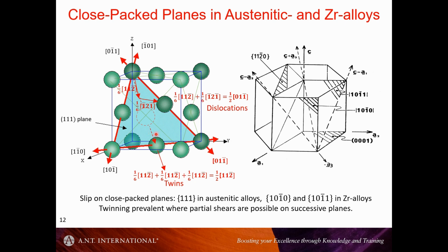In the case of the austenitics, I mentioned the twin operation, as you may or may not know, and again I can demonstrate this with some ball models later, or certainly during the presentation, but I'm also going to be attaching some YouTube links to demonstrate what's going on with a ball model with twinning. But basically you've got slip on 3 planes.